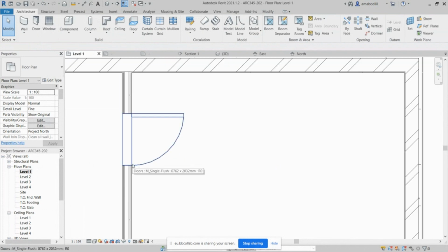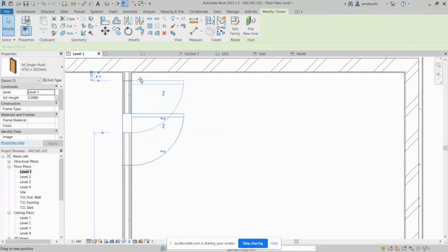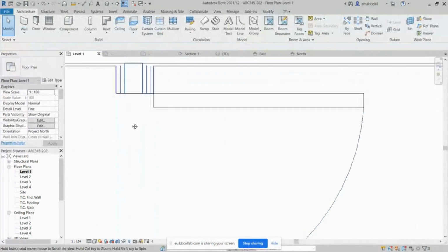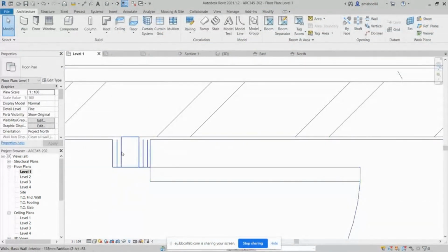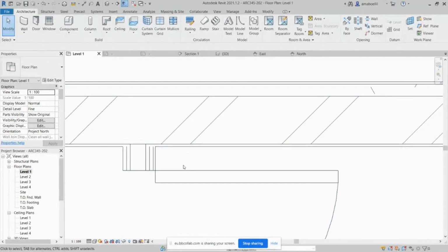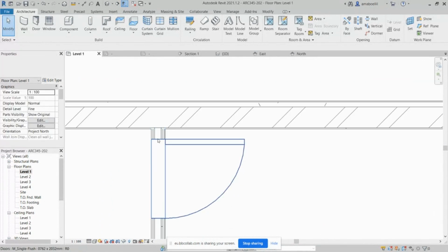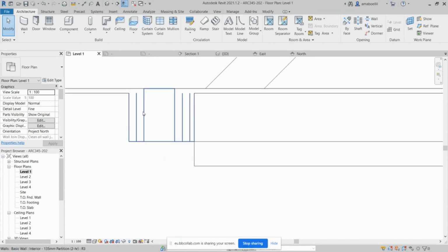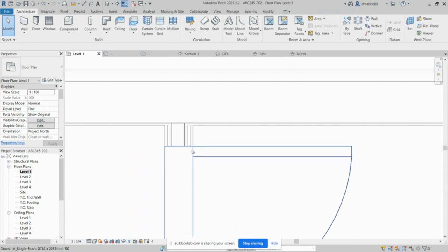The placement of the door is ... a proportion of a wall here that is not less than 60 centimeters, or you can make it so that once you place it, the brick that you build with is going to be accommodated completely here, so that you don't have half a brick or something. If your brick is 20 centimeters in length, it's better to make the door 20 centimeters away from the wall, because once this is built in the wall, placement of the door is not going to be an issue. Otherwise, it's going to be very hectic for the mason when he wants to construct, to cut this in half. It's not doable, even. It's not going to be professionally done.